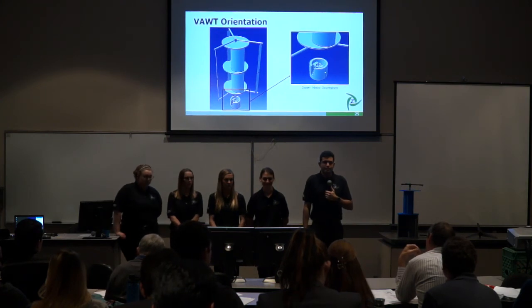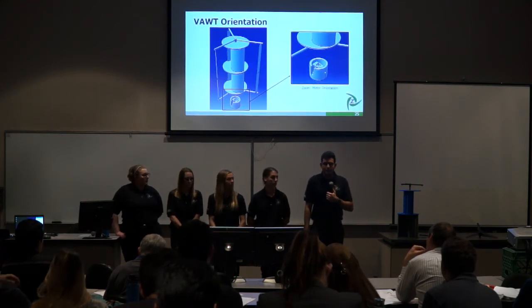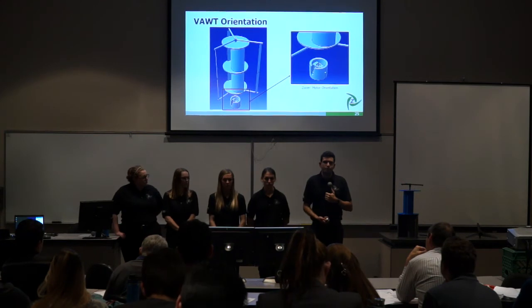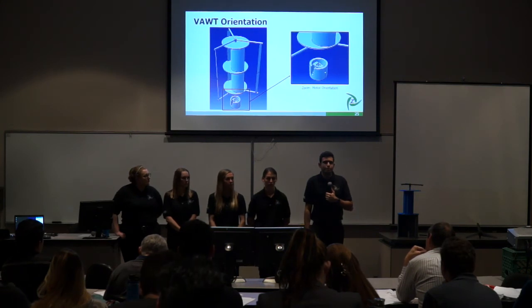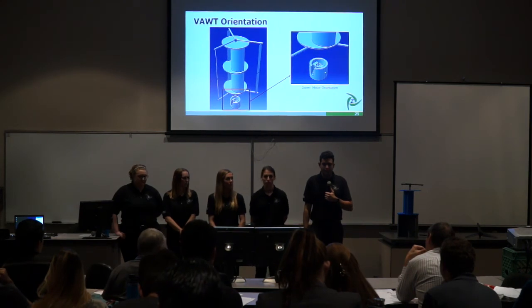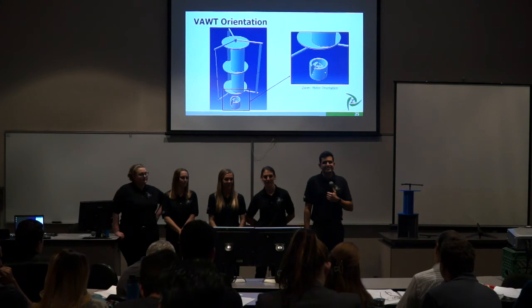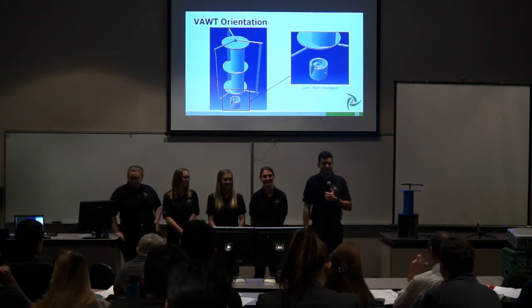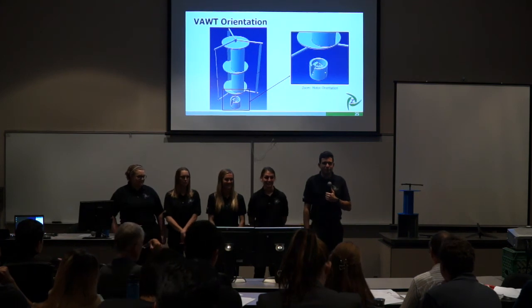Is there any way you'll be hitting it with more than 30 volts DC? And will it burn out there? Based on our calculations from the motor testing results, at a rotational speed of 1400 RPM, we only got a voltage input of around 18.6 volts, I believe the number was. So we don't expect the voltage to get up to the 30 volts. Sounds like a low number before you get going so fast. Yeah, that might be an issue as well. That's why we're doing the tip over analysis to ensure it doesn't blow.